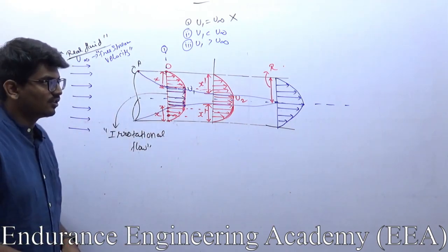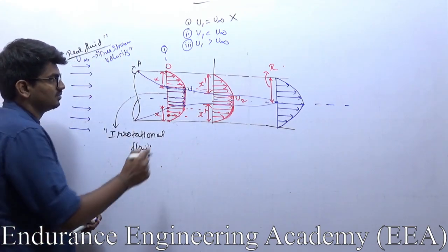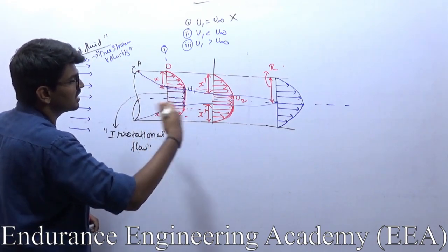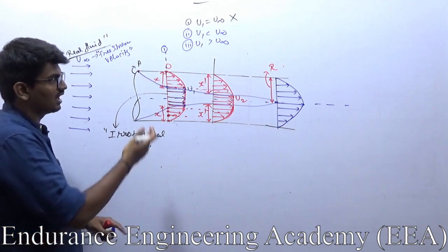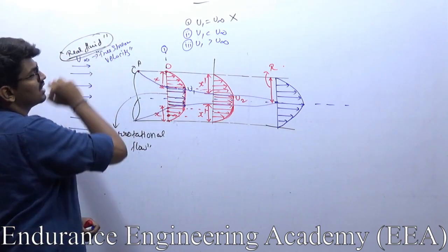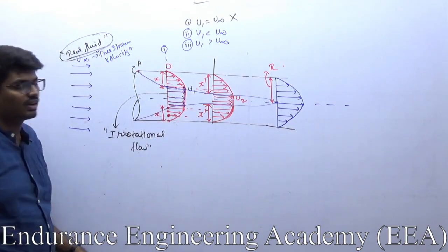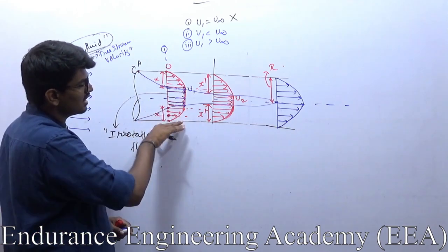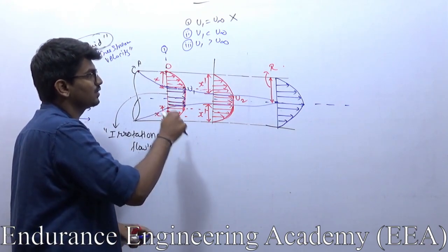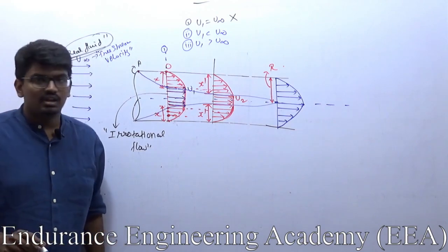Since it is an ideal fluid flow, and the velocities are the same, there is no possibility for rotation here. Even though it is a real fluid, the velocities are constant everywhere, so it is irrotational. But if you see here, velocities are varying, which is behaving like a viscous fluid. There is viscosity, so here the flow will be rotational. Okay, right.